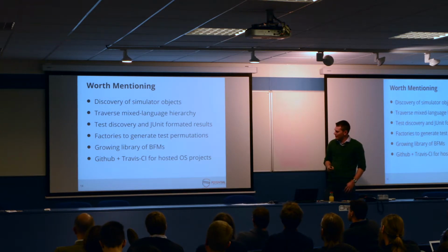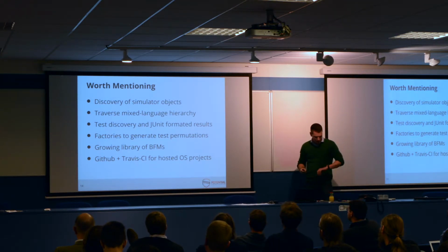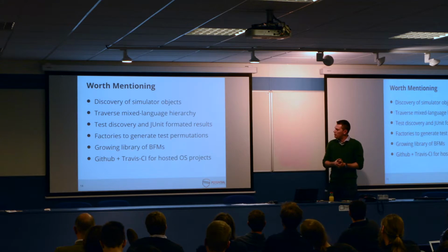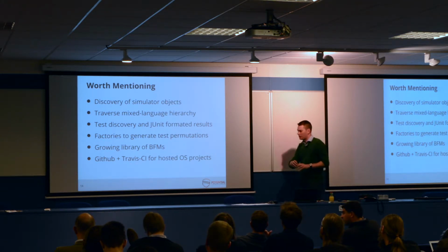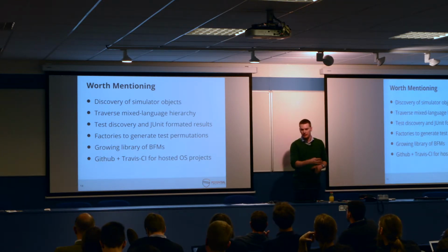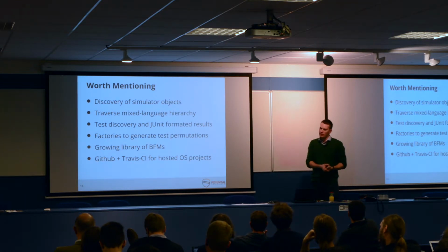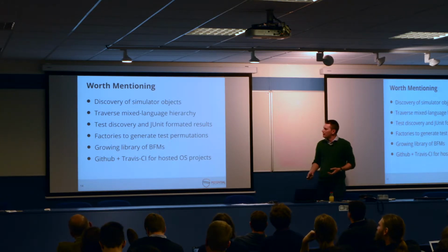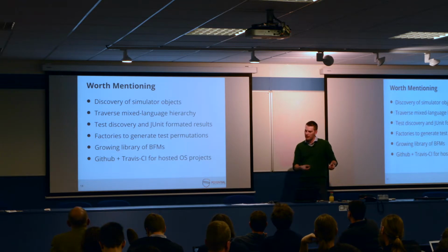Right, so there's a whole load of stuff that we won't go into because we're running behind. But you can do things such as dynamically discover all the objects in the design, automatically attach protocol checkers to all buses that match a certain naming convention or type. You could automatically insert cross-block domain checks and things like that.